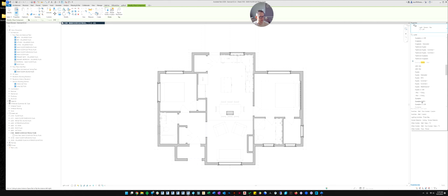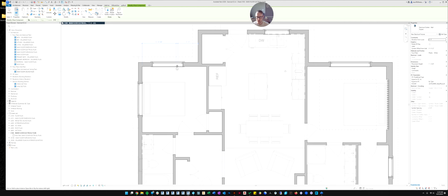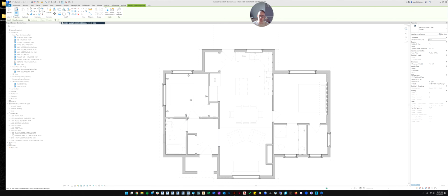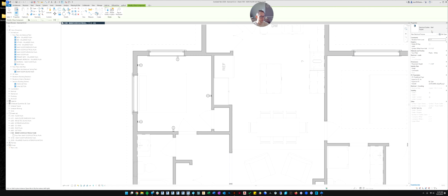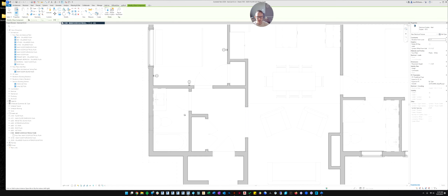You can look at the other kinds of outlets, but let's just hurry and put in a couple duplexes around the room like we did before. I'm not going to spend the same amount of time showing you since we've already been through this. It's just to show that they look roughly the same. And then when we go to do GFCI, we can just come here and click that. And again, over here, if you click placement height, we can put these at 4 feet high.